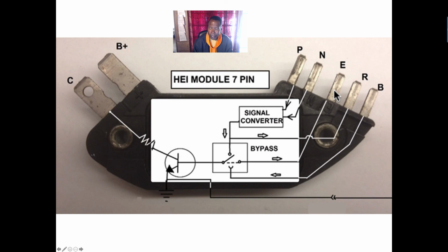I think this arrow is going the wrong direction. Right? From this EST circuit, it's going through here to the base of the transistor now to control the timing at different load situations. Again, the same way. A positive signal here, I complete the ground from the collector to the emitter to ground. A negative signal here, current does not flow and the coil fires. That's your circuit. Understanding this circuit will help you troubleshoot a no start condition with no spark.